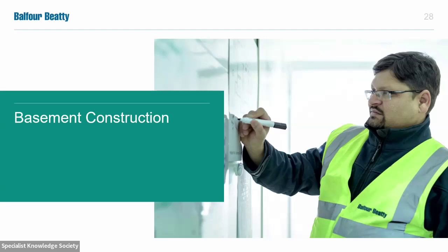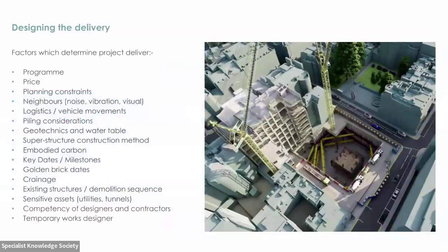Okay, so that was a quick scan through diaphragm wall construction, and hopefully that links back to the slide we had around managing geotechnical risk, and you can see the number of aspects that were all combining together to be able to make that wall work properly. Diaphragm walls, or secant walls, or contig walls, or sheet pile walls can all be used in basement construction. So you can have basement construction where you're putting an embedded retaining wall around the site, and you may have piles in the middle to support a structure.